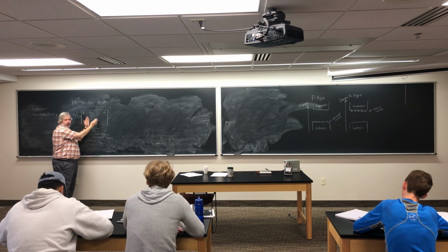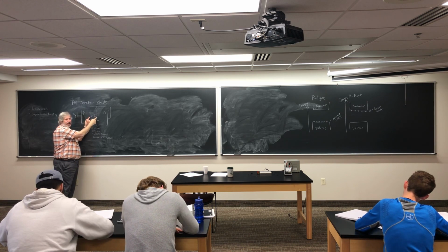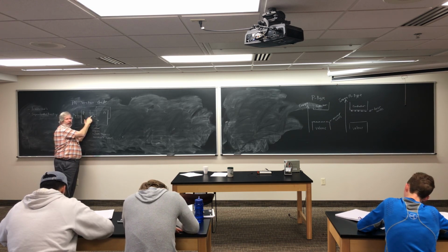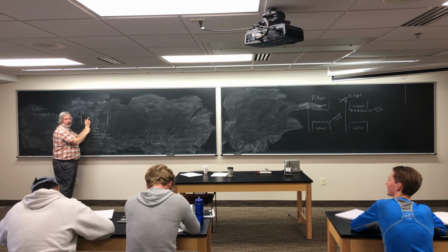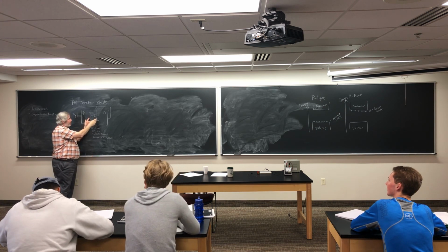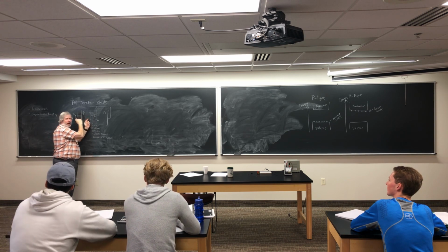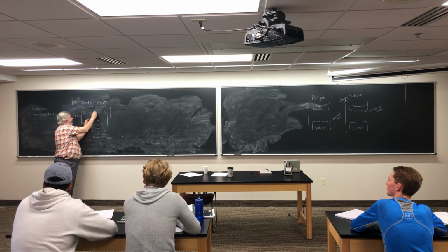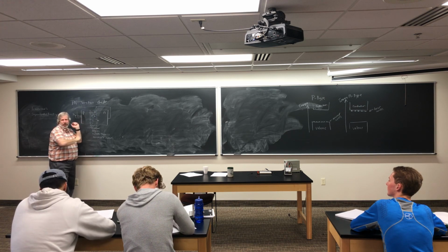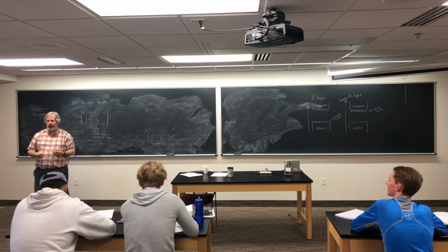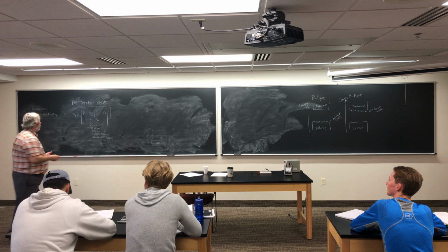We said that when those electrons that were here combined with those holes here, this thing was electrically neutral. But now we've moved electrons over to this side of the junction and holes over to that side. Since that was electrically neutral and you've gotten rid of electrons, this becomes positively charged, this becomes negatively charged instead. In this region we created an electric field. Okay?